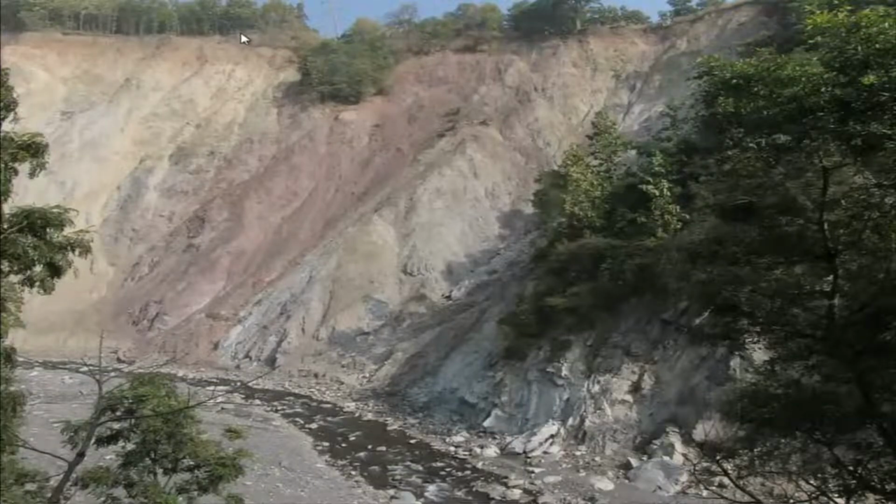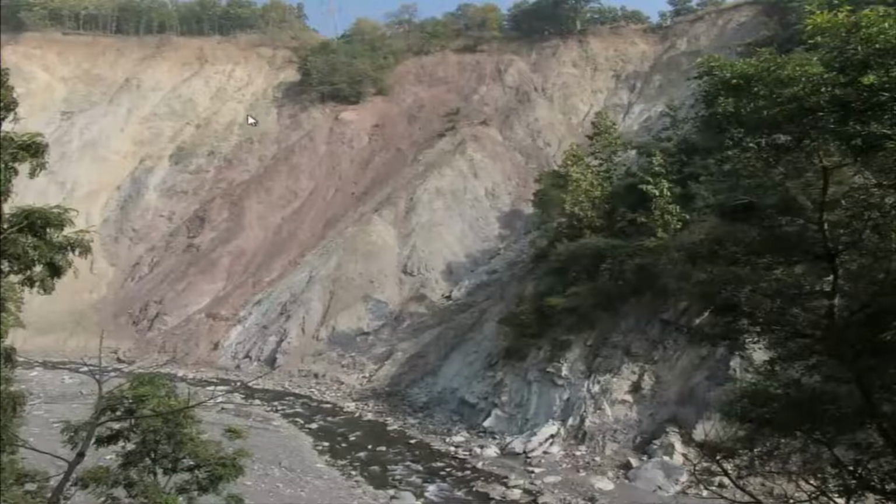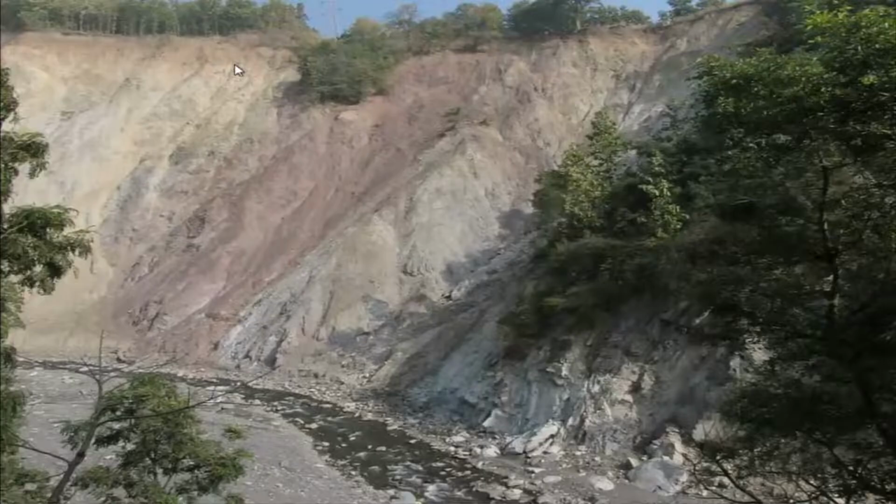at this height. So, this means that, as we were talking about, this forms a part of terrace, and terrace is sitting so high, the incision is almost like 70 to 80 meters. So, it has cut the alluvium as well as it has cut the bedrock. So, please remember the previous slide where we were talking about the erosional terrace, which is formed and which incises the alluvium as well as the bedrock. So, bedrock is also eroded, hence it is also termed as Strath terrace. This is an example of Strath terrace.